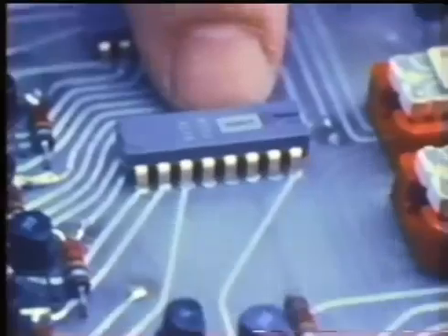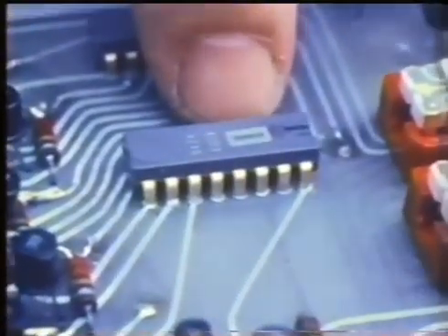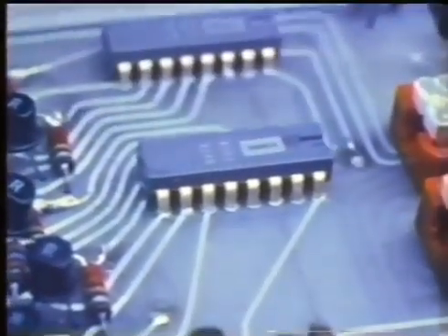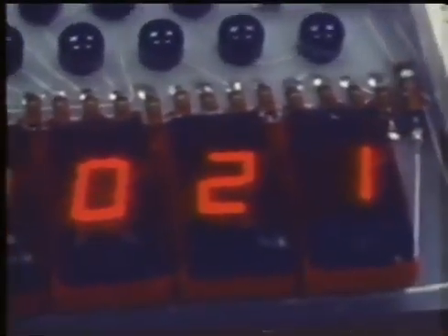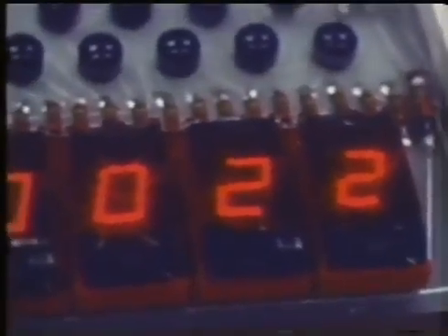I/O and RAM group instructions allow the interface of a keyboard to the computer, and encoding can be done with microprogramming. The 4003 10-bit static shift register is used to expand the number of I/O ports. The interface and encoding for 7-segment displays may be done by microprogramming, and an output port may produce clock pulses for loading data into the 4003.